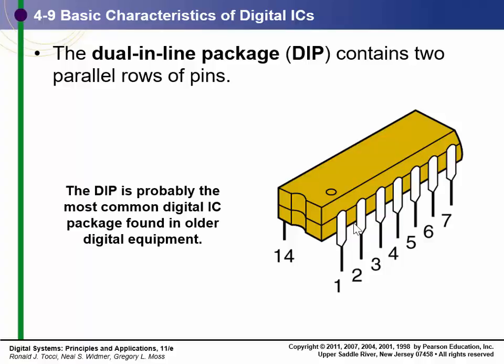So you have the surface mount and you have multiple layers of the board, because the boards have gotten much denser. This chip is showing a 14-pin chip. All the chips we've talked about thus far, the AND gates, the OR gates, are all 7400 parts. Those are all 14-pin chips. The programmable logic chip that I brought in the other day had well over 250 pins on it. Well, if you have 250 pins, that means you've got a lot of electrical connections to make into a very small area. So 2 layers is not enough anymore. So that's a challenge for the circuit board designers.